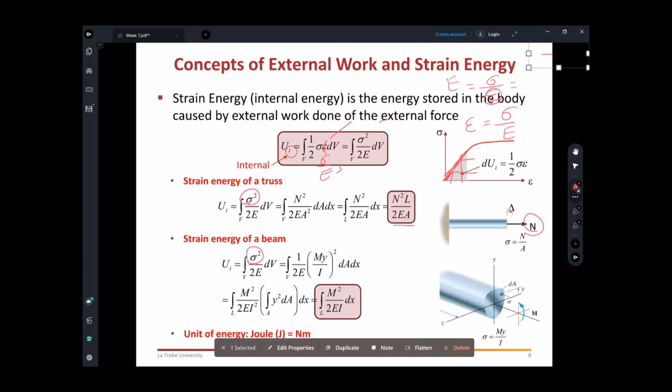If you bend the members like this, then it's called bending stress. When you pull the members, it is the axial stress. Axial stress is equal to how much load I am applying over the cross section. That is done in the truss members. It's just the axial stresses. The truss members don't have any bending moment, so therefore we have this load over area.